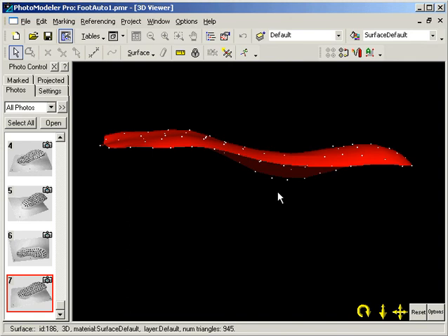From that, you can determine whether you have made sufficient number of spans to fit the surface you want. This is a single NURB surface, not a triangulated one. It can be exported to the various formats that can handle NURBS elements. NURB surfaces can also be exported in triangulated form for those formats that do not handle NURBS natively.